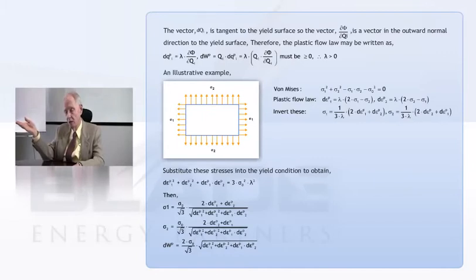One of the interesting parts of that is that if you do that, you can show that Massing's hypothesis, remember that about taking the loading curve, flipping it twice and doubling the size, and then tagging that on to where you stop loading, that was Massing's hypothesis. And this material satisfies that. And that's a good thing, I think, particularly if you're interested in single crystals, and a lot of people are.